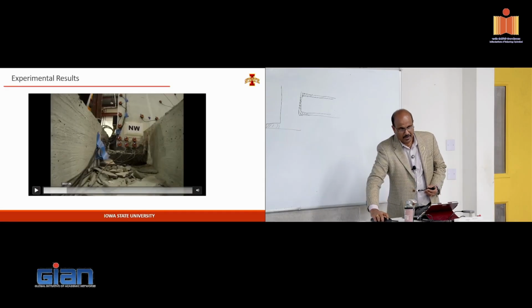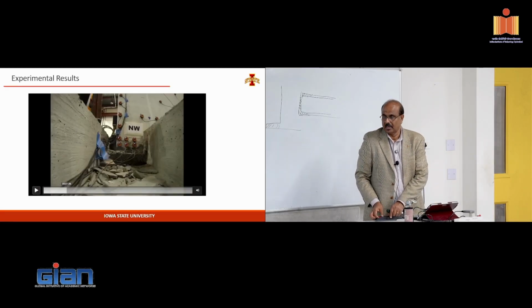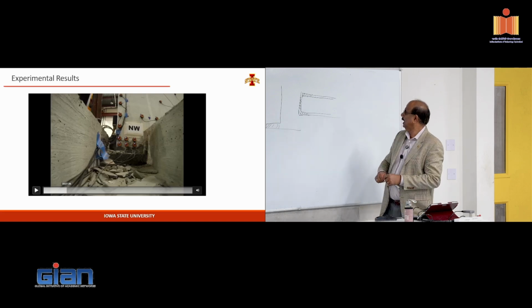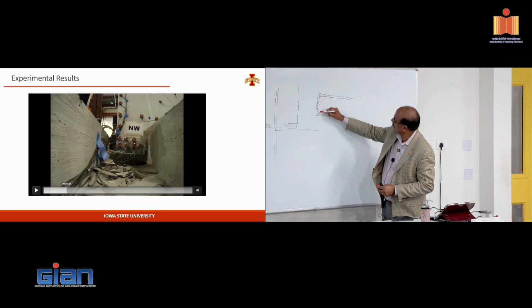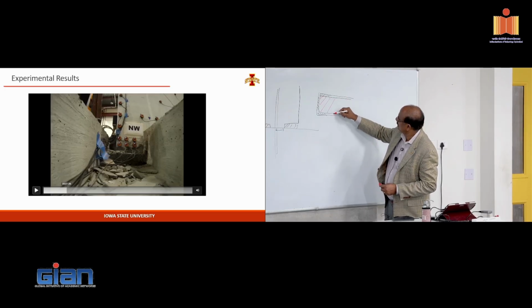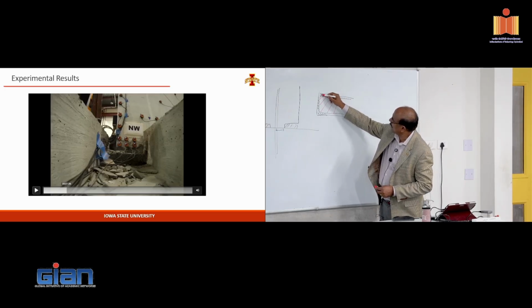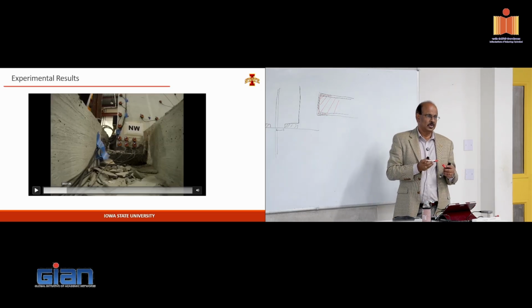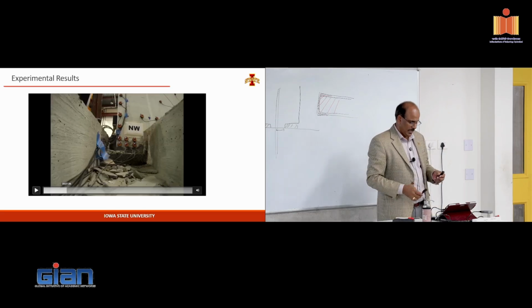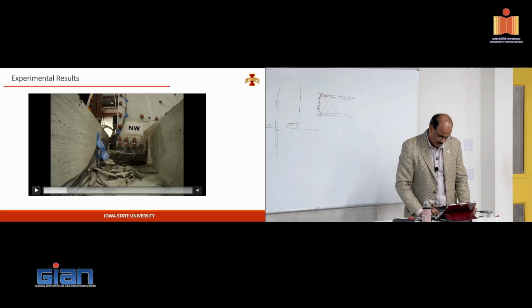So in the final test, what we did was we eliminated the steel channel, and we only put the grout just underneath this core region, so that they don't actually experience any impact, all of this cover region. And that actually solved the problem. So you don't need to put the steel channel and still prevent that spalling that you're seeing here.